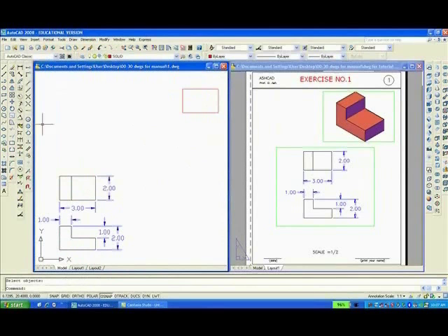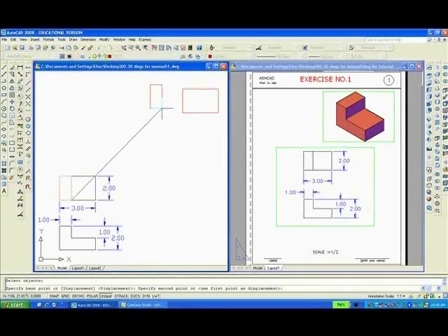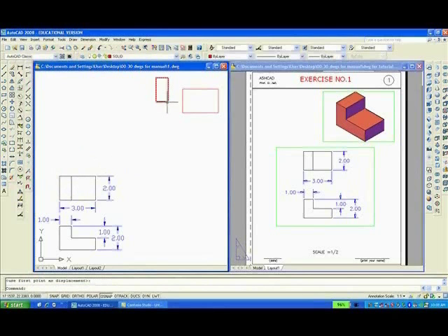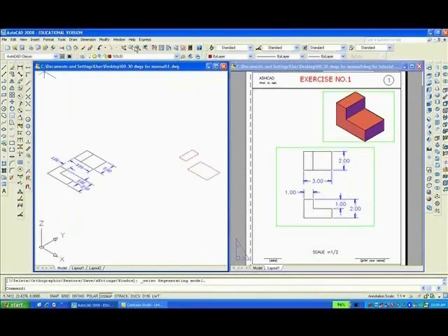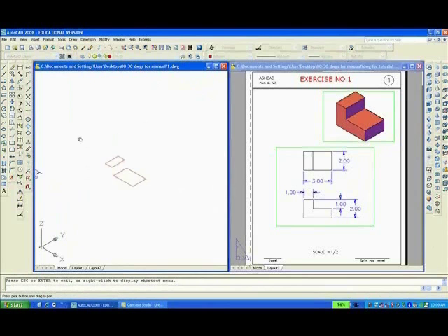No, try it again. We'll do the rectangle command one more time on the smaller rectangle like that. M, enter, L, enter, and move that up there. Your next step will be to move into southeast isometric view. Then you'll want to pan and zoom to enlarge what is going to be the solid model.